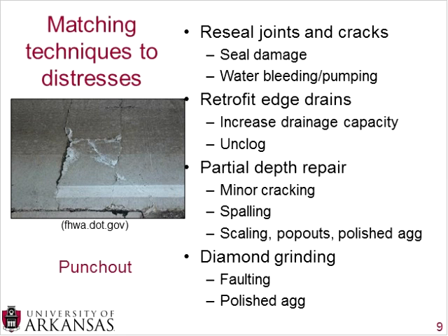By resealing your joints and cracks, you may slow the water bleeding and the pumping, but you're actually not solving the fundamental problem, which we'll go over in the next slide. So resealing joints and cracks can reduce water bleeding and pumping, but it will not actually eliminate the fundamental problems of them.